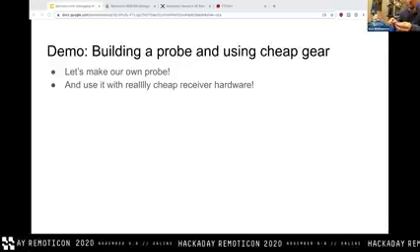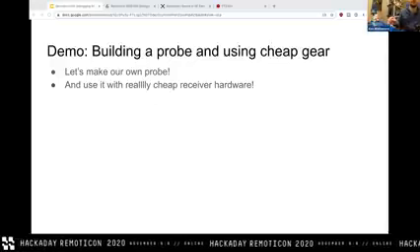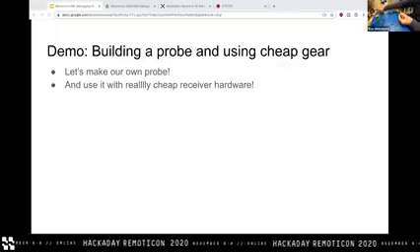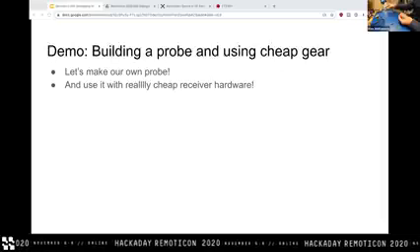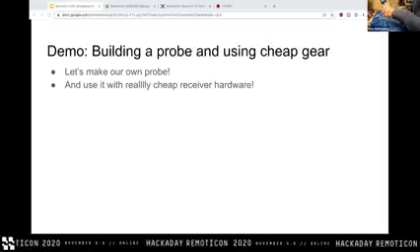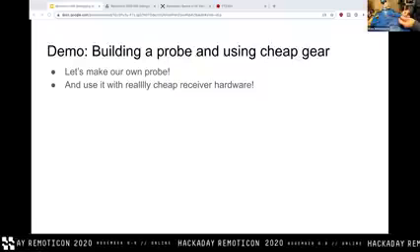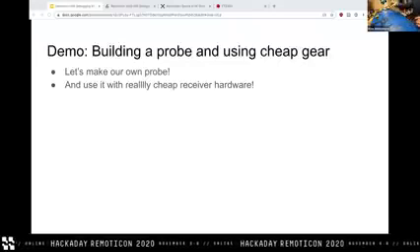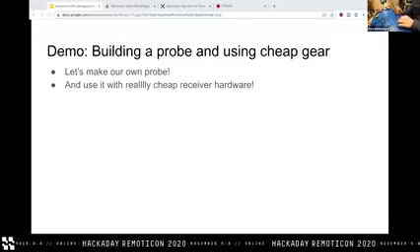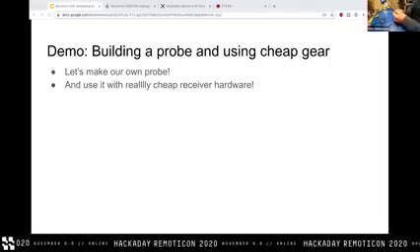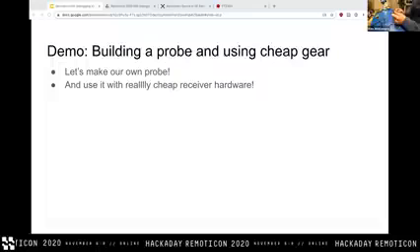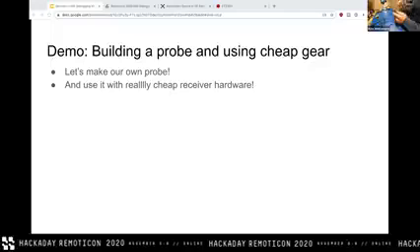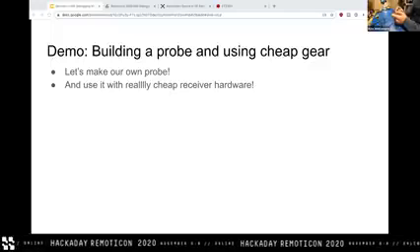So this might be impossible to see, and I preemptively apologize if it is. If this is roughly equivalent to this guy, albeit without any shielding, then these two are roughly equivalent. And really all we need to do is make a loop of wire as small as we can possibly get it. And there are a couple of key differences that I've found in practice don't appear to actually matter all that much. One key difference is it's really important where the active area of the probe is, and the definition of active is where there is and isn't shielding, at least nominally.